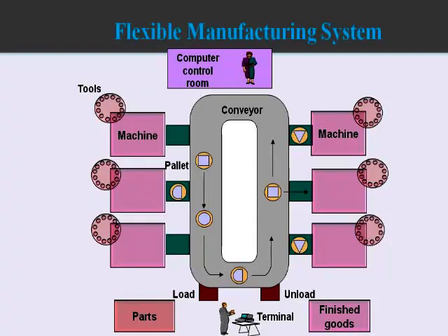Once the machine is processing the program, the tool selection and the tool life, how much is the remaining life of that particular tool, are all automatically recorded, and in the automatic tool library maintained by the controller, all this data is appended. So we'll come to know what is the remaining life of the tool on each machine.